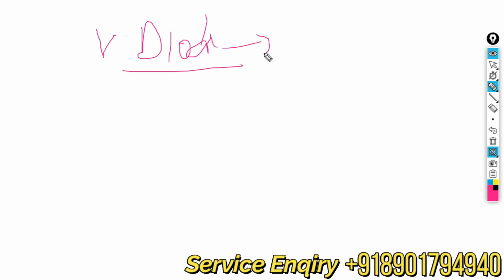What are the things? Let's say from the starting, the diode value is okay, right? So we do not work on it, the diode value is according to spec. Now when we connect a charger with the battery, you will see a little current consumption, and suddenly it drops in the next second. But when we measure on the VPH voltage, you will see the current consumption without battery. Also there is a 2.1 voltage,